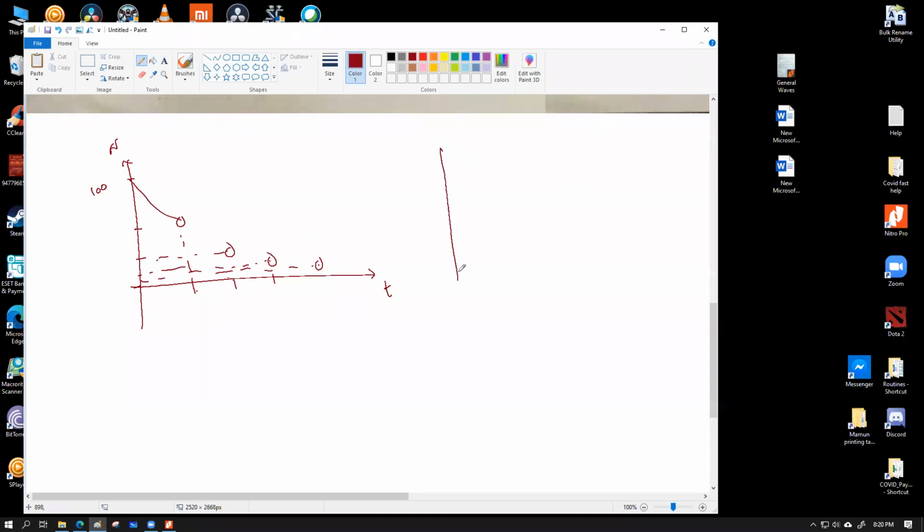So you're having an equal proportion of drop after every half-life. For a capacitor, that's going to work by 37%. So if you start with a fixed amount of current, for current versus time over here, if you start with a value of 100 for current, after a tau amount of time, that's going to become 37. That's going to be one of your points. And after another tau amount of time, let's say 2 tau, that's going to be 37% of 37. How much does that come?